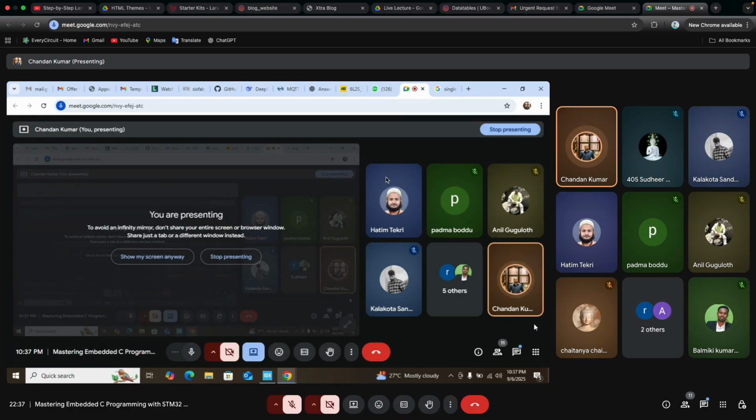So these are the components: a start condition, slave address, third one the read/write bit, acknowledgement or not acknowledgement, data bytes, and stop condition. There is one more element in the data frame, that is the acknowledgement or not acknowledgement bit.